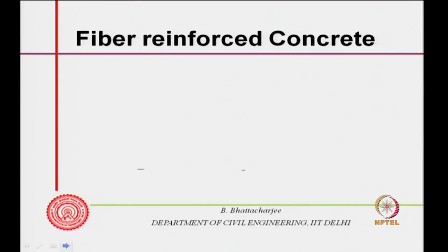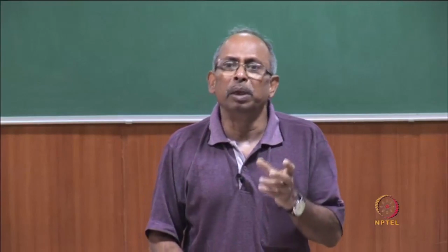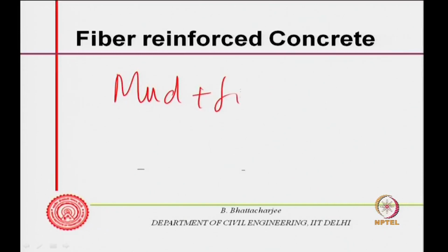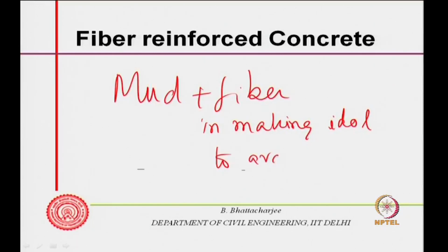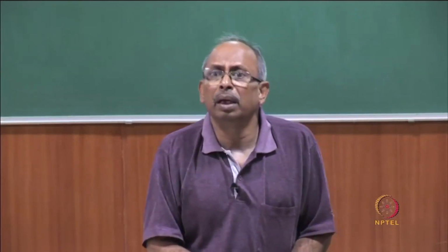Now, fiber reinforcement has been used for many years in materials. For example, you use fiber reinforcement with mud, mud plus fiber, in making idols, to avoid shrinkage cracks, drying shrinkage cracks. This has been there for many years, or in similar other materials, you put fiber which can arrest the